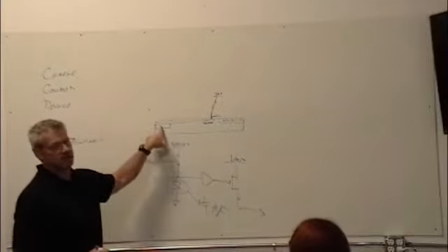So what they did was, there's, again, two ways to do this. You've got your P plus here, and as you drove the holes out, they did what's called a buried channel here, where it was really heavily doped, like P+++ maybe.